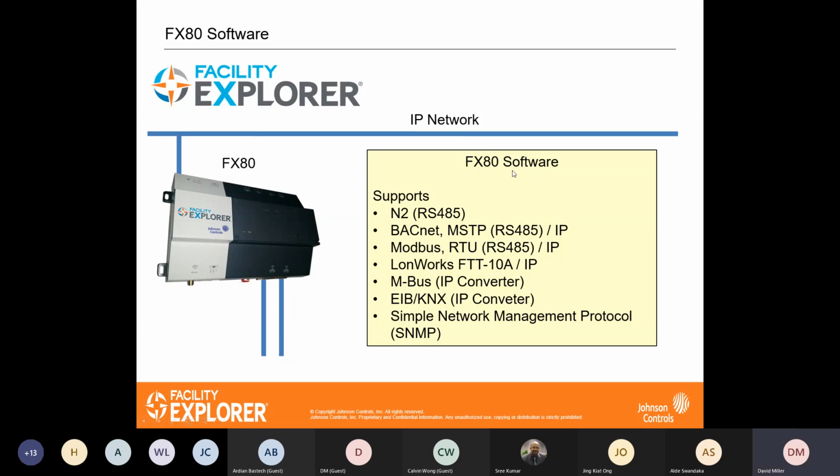So the FX80 software supports as standard ED2, which is an RS485 protocol, BACnet MSTP and BACnet IP, Modbus RTU and Modbus IP, Lonworks FTT10A and Lonworks IP.